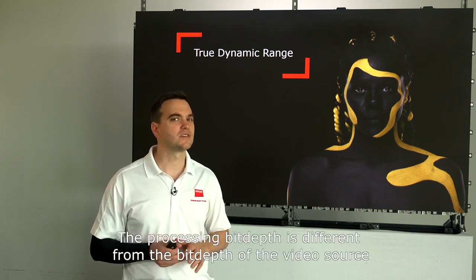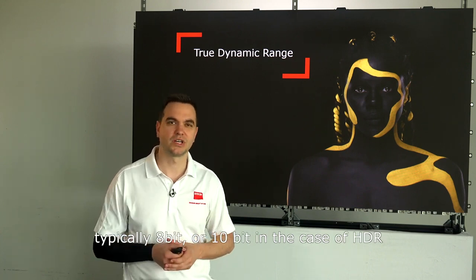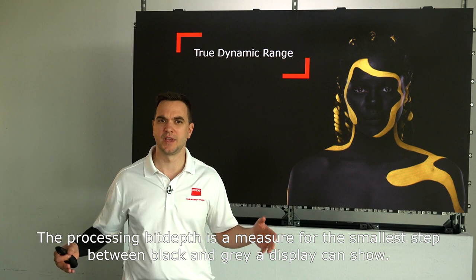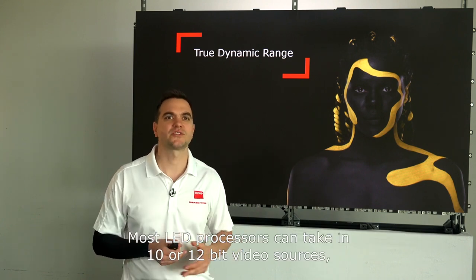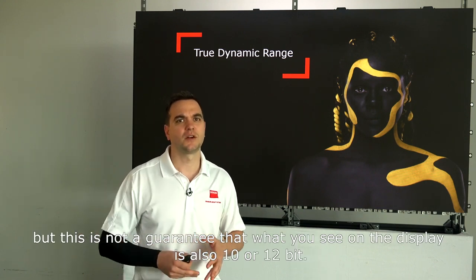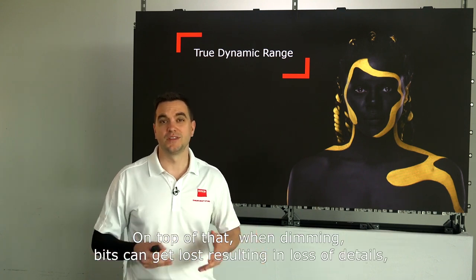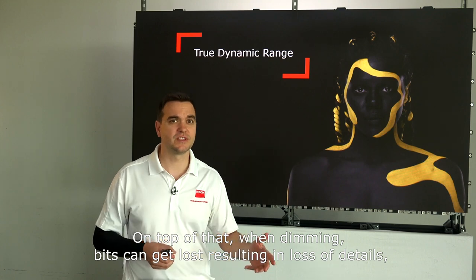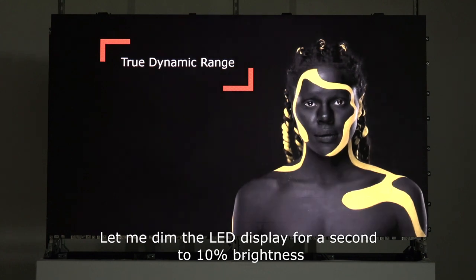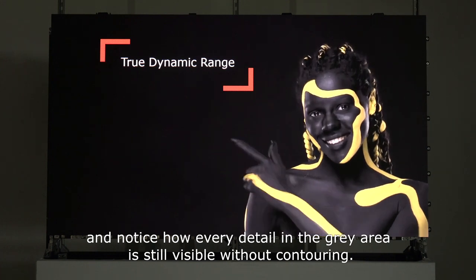The processing bit depth is different from the bit depth of the video source, typically 8-bit or 10-bit in the case of HDR. The processing bit depth is a measure for the smallest step between black and gray a display can show. Most LED processors can take in 10 or 12-bit video sources, but this is not a guarantee that what you see on the display is also 10 or 12-bit. On top of that, when dimming, bits can get lost, resulting in loss of details visible as contouring. Let me dim the LED display for a second to 10% brightness and notice how every detail in the gray area is still visible without contouring.